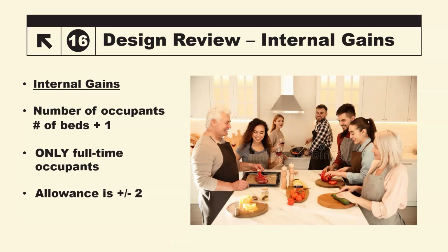So if you have a builder doing Energy Star as a compliance pathway in lieu of code, they're doing it in that range for Energy Star, which is plus or minus. So what should and can be considered is full-time occupants, but not guests. In other words, we can't really design for 15 plus occupants to oversize the equipment for a July 4th party.